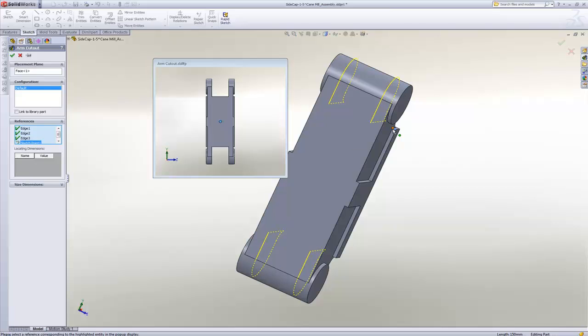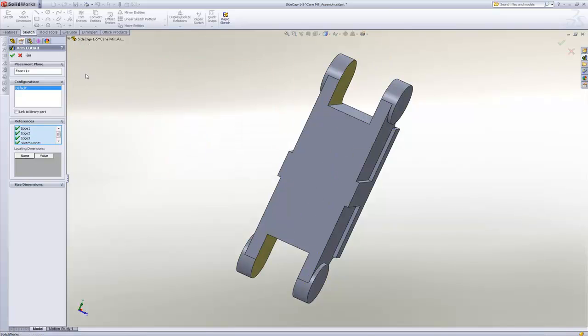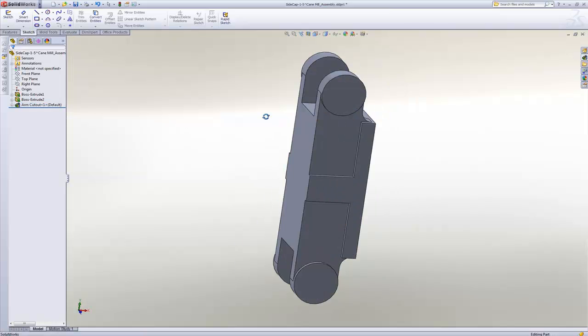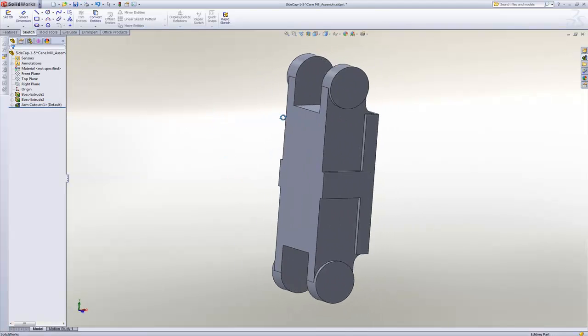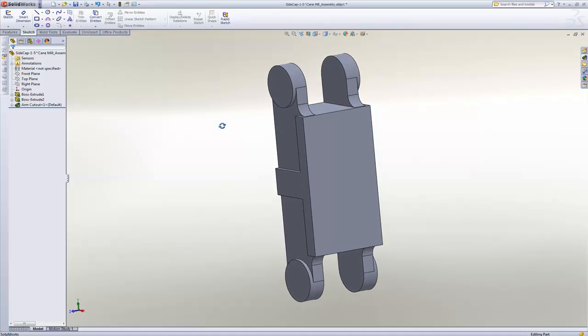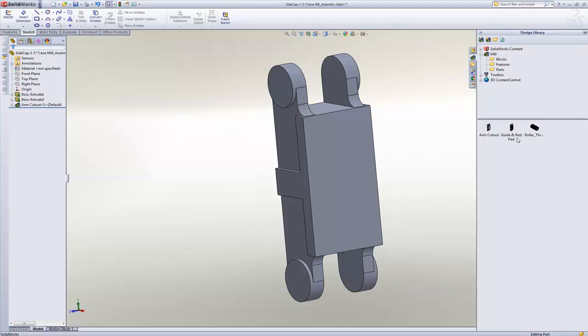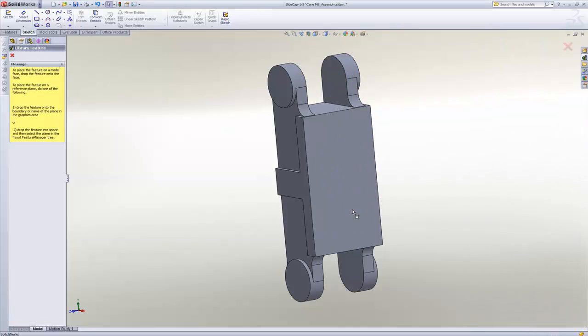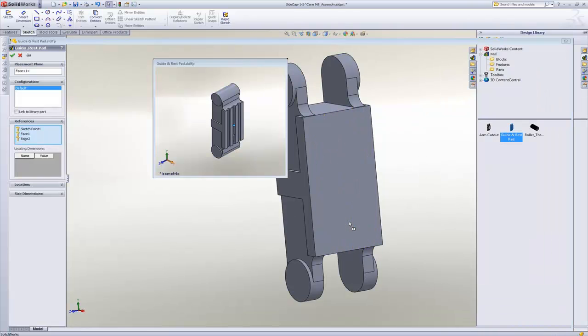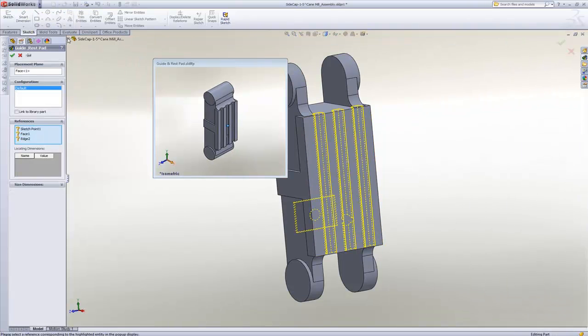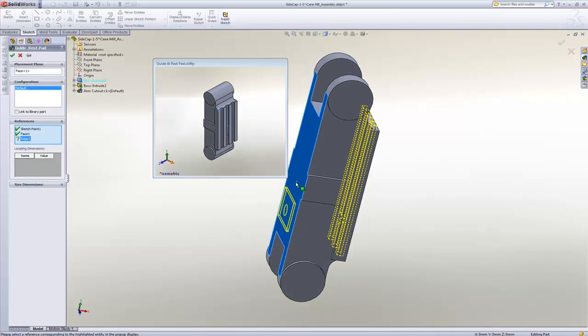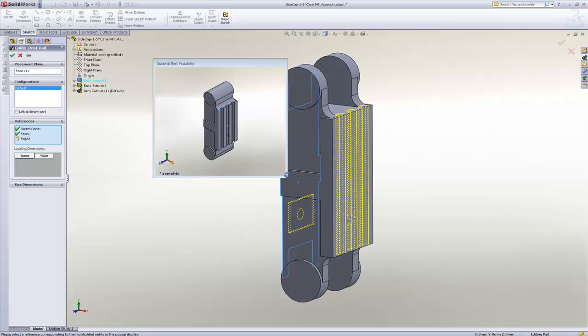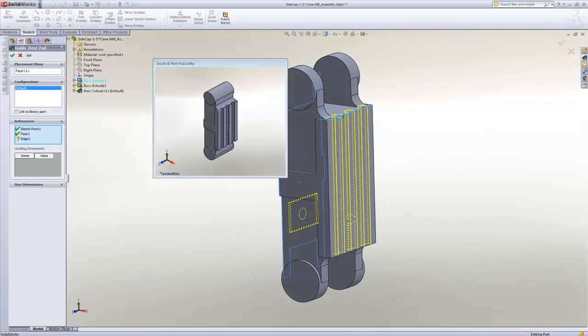Let's now form the side cap arm and the guides where bottom bearing slides. We have just formed the side arm. We'll just go ahead and drag in the guide feature from the design library. The necessary inputs in this case would be a sketch point, preferably origin, and couple of edges that would help us in locating the face of the pad onto the bottom as well as the guide edges.